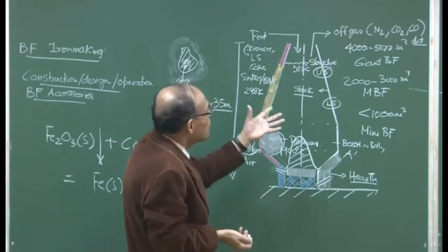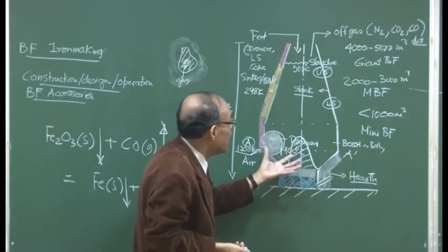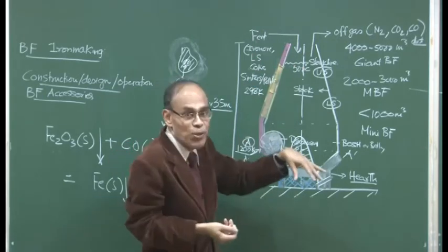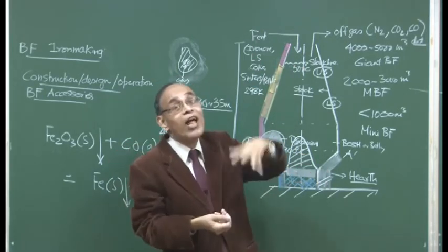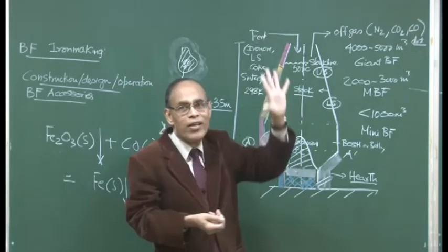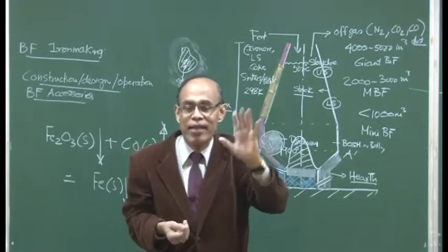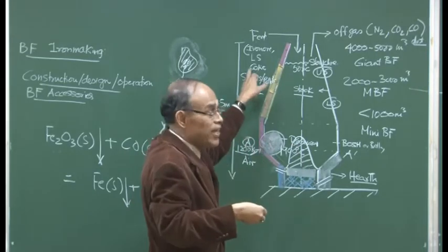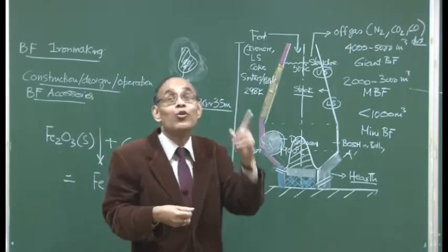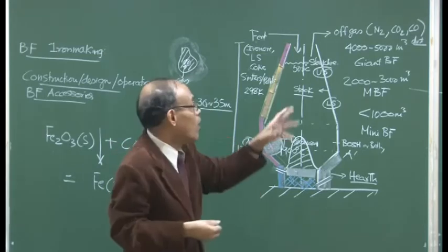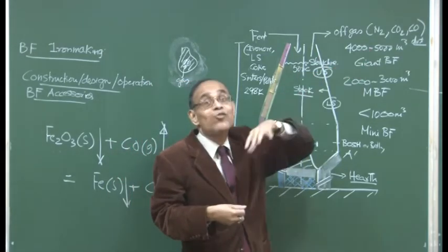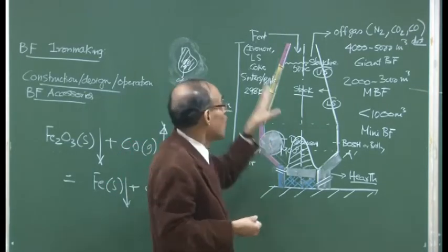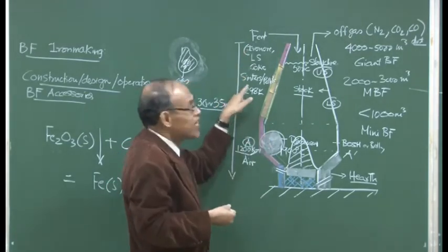Anyway, the major objective here is that we have to charge material inside the furnace periodically, and yet we cannot allow the material to go out of the furnace. This is the foremost requirement, that we will use the top to charge all the feed materials, but at the same time we will not let a single molecule of this poisonous dust laden gas go out into the atmosphere.